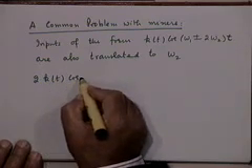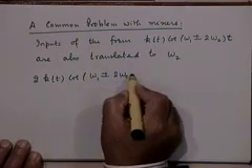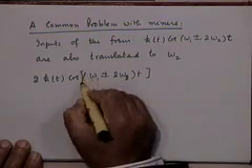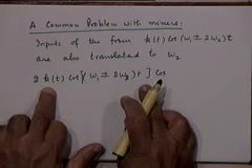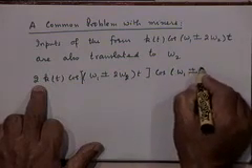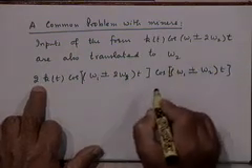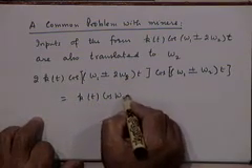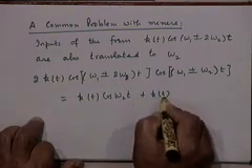What we are saying is kt cosine omega 1 plus minus 2 omega 2 t, when you multiply that with 2 cosine, what are you multiplying with? What's your local oscillator frequency? Either omega 1 plus omega 2 or omega 1 minus omega 2, right? This leads to two components, one which is a difference frequency component and the other which is the sum frequency component.